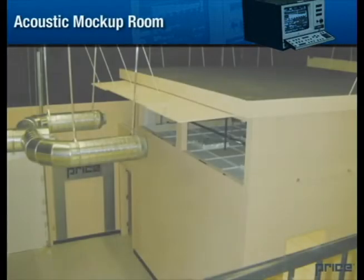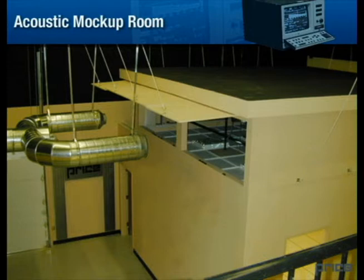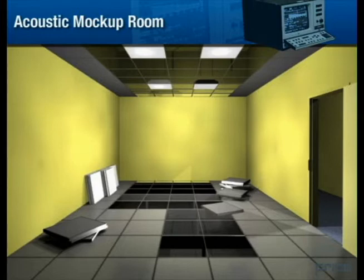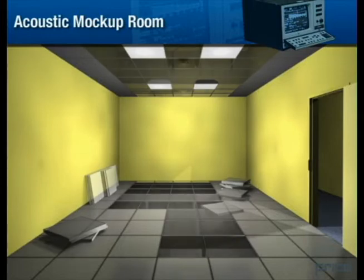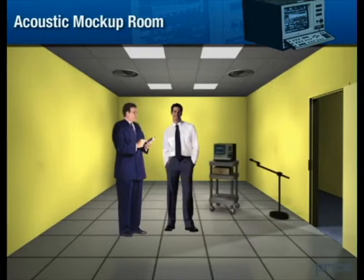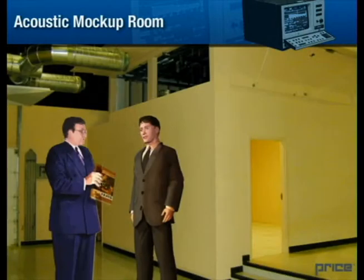Acoustic mock-up room. In order to demonstrate and experience real-world scenarios, Price has constructed a test room specifically for conducting acoustic mock-up tests for terminal units. The room has been designed and finished in accordance with acoustical consultants' guidelines for simulating actual office acoustics. Mock-ups can be developed for each project's unique specifications, including terminal unit type, size, air volume, ceiling construction, etc. Acoustic mock-up tests are a very effective method of verifying room NC levels as opposed to relying on theoretical calculations for terminal unit applications. Visitors can listen to the system in operation as well as be provided with sound measurements.